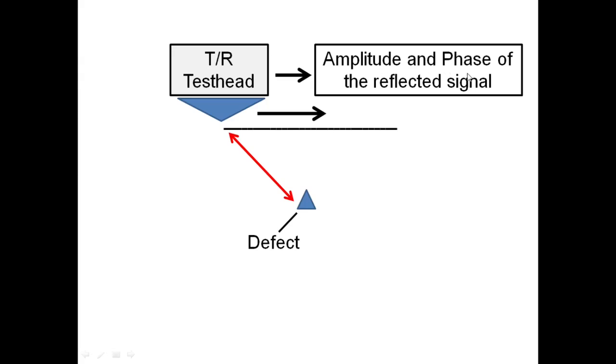Well, the phase, you remember, is a measure for the length of the travel path, that is forth and back. Normally a length is given in meters. We can give it also in number of wavelengths, and considering that one wavelength is 360 degrees, we can also give that as a phase in degrees.